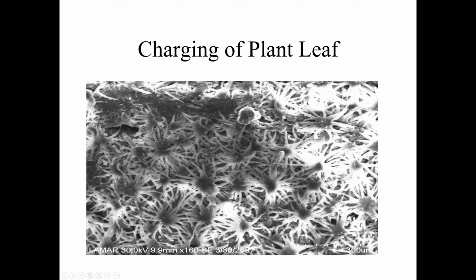Okay, images. This is the fun part. This is a plant leaf that I took from outside and put on the microscope. This is a secondary electron image. Basically it's charging up the sample, and it's just repelling the electron beam. That's why it's got this spotlight effect where it looks like it's being hit by a floodlight. This image is not usable, period.